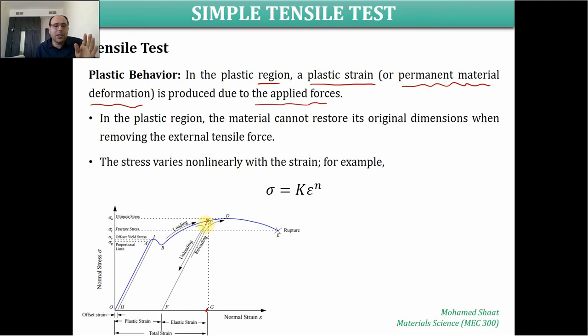But for some reason, if we decided to stop the stress, to remove the stress, the material will restore back again in that way. It means that there will be a kind of spring back. So the difference between the total strain at the instant that the force is still applied, once we remove the force, the material will spring back. This is known as the spring back behavior of the material, and this depends on the stored elasticity or restored elastic energy within the material. This is known as the spring back of the material.